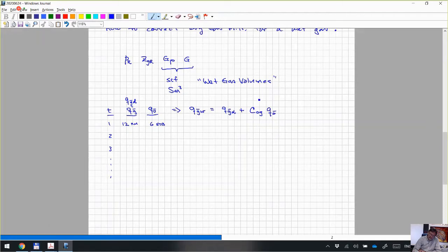This term here has units standard cubic feet per stock tank barrel. So it's the fake equivalent surface gas. If you could turn these 6 stock tank barrels of oil and vaporize it into a gas at standard conditions, then that number is typically around 500 to 700, somewhere in that range.